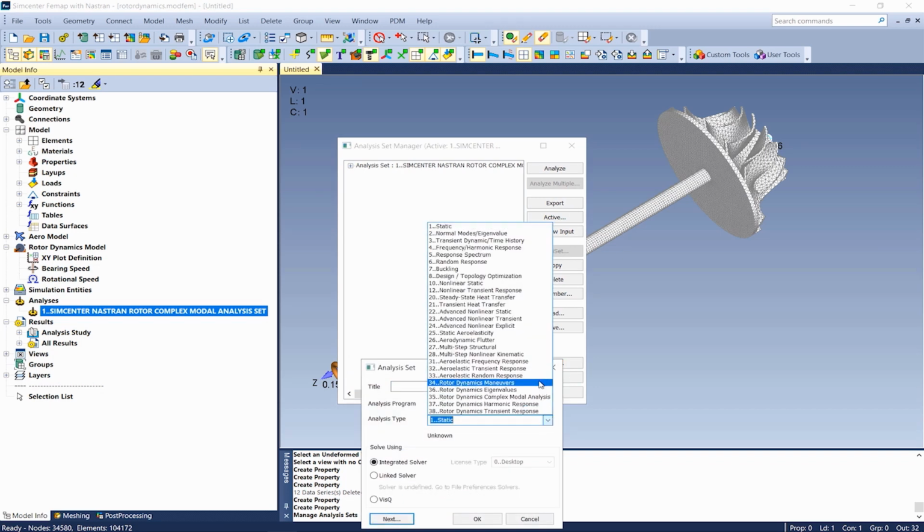Rotor Dynamics Solution 414 has 5 new analysis types. Solution 414-101, Maneuvers, is a linear static analysis with rotational forces. Solution 414-103 is an eigenvalue analysis that computes modes of the system at rest. Solution 414-110 is a complex modal analysis that's used for finding critical speeds and analyzing the stability of the rotating system. Solution 414-111, a harmonic analysis for frequency-dependent excitation. And finally, Solution 414-129, transient analysis.